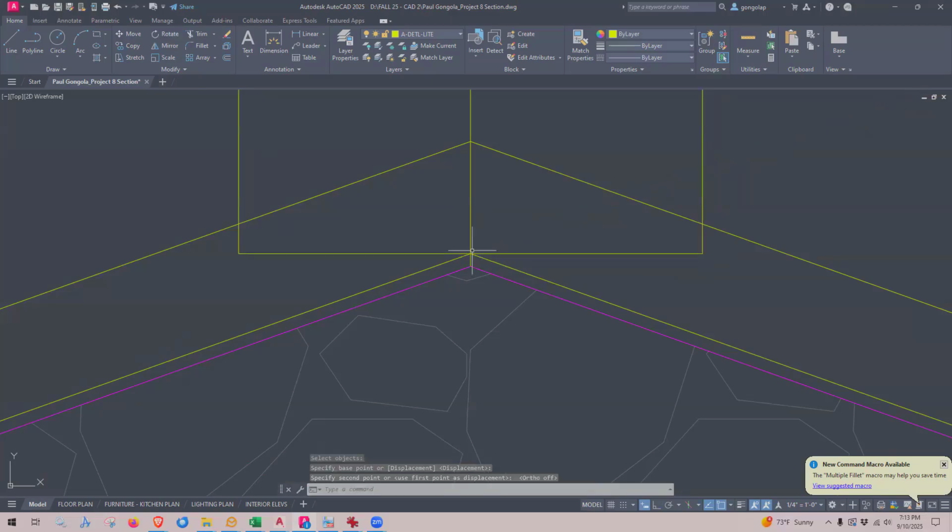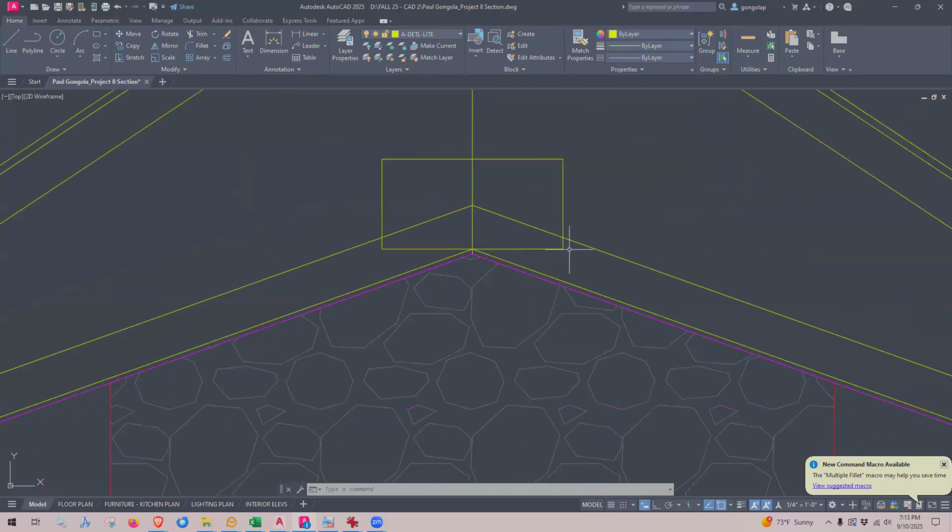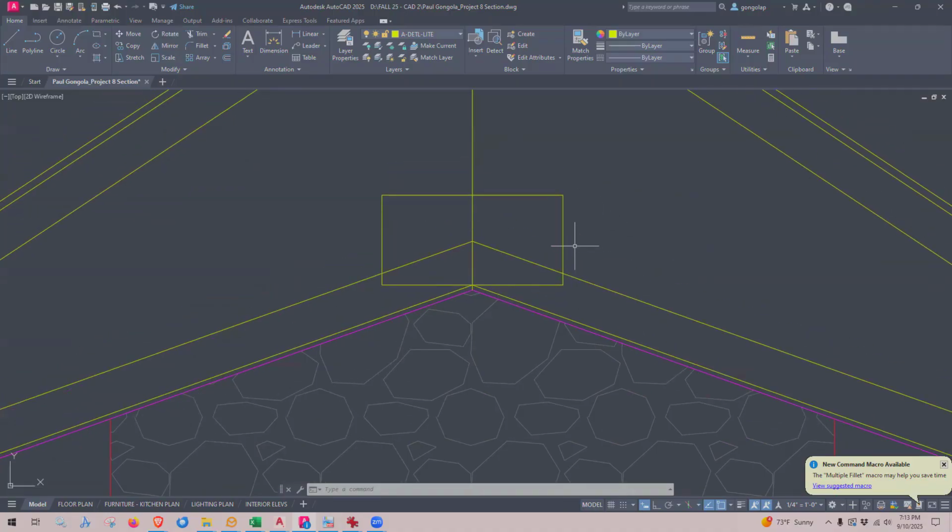This point right here. So the drywall, remember, this is the ceiling drywall. It comes up and then comes down, and right above it is this plate. And this plate is supporting these ceiling joists. They're actually bolted into this plate. So this is a steel plate, and there are bolts here that are bolting these ceiling joists in place.